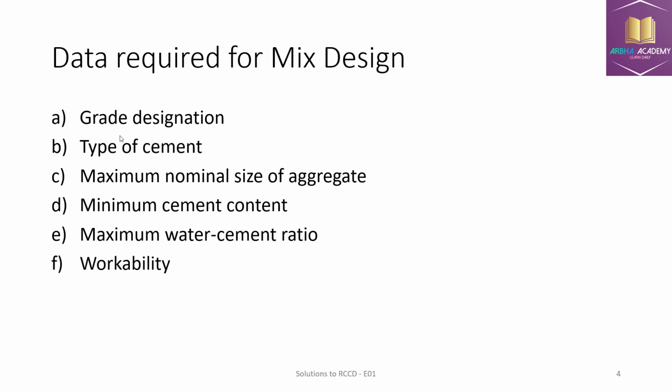And then workability of the concrete, whether it needs to be pumpable or whether it is self-compacting concrete. So all these things need to be taken into consideration, because for example, if it is self-compacting concrete, SCC, then the volume of coarse aggregate will be much more reduced and the volume of fine aggregate will be increased in order for the more workable and self-compacting condition to occur in the concrete.